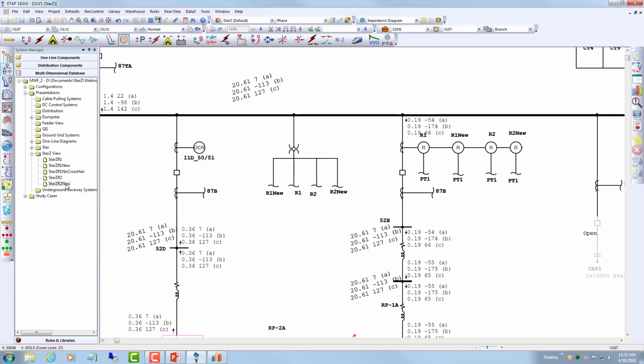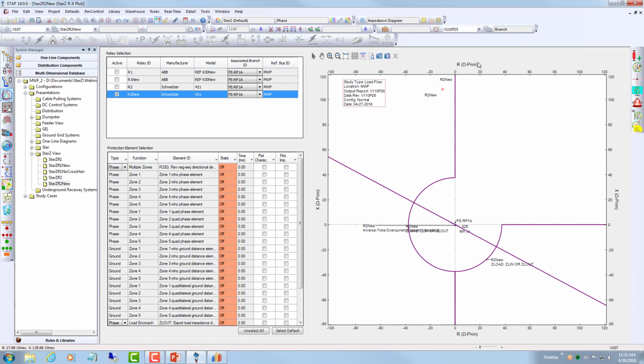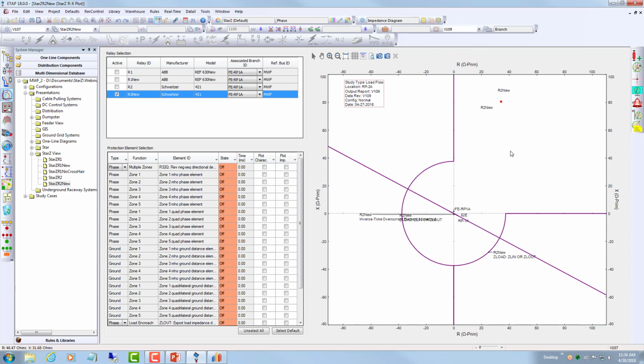So that's basically the solution, but there is still the same issue with the ABB relay: if there is that rare condition where there is an over voltage in the system and voltage is very high, 9%, 8%, then in this case, as you see here, load encroachment is not going to block and the relay is going to trip. If I remove that, the relay is going to trip because there's nothing else to block the signal. So that's again the issue.